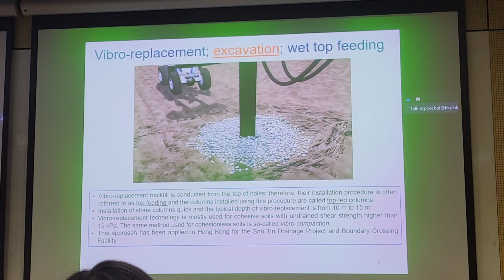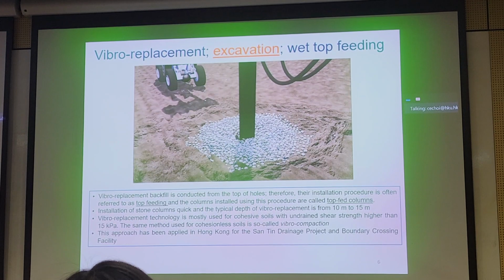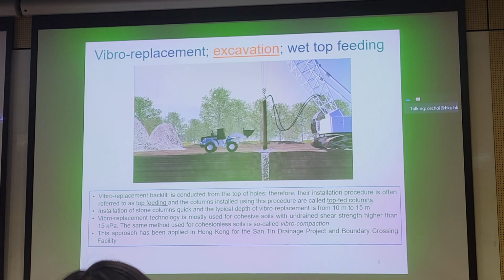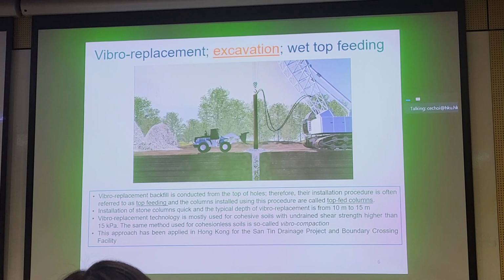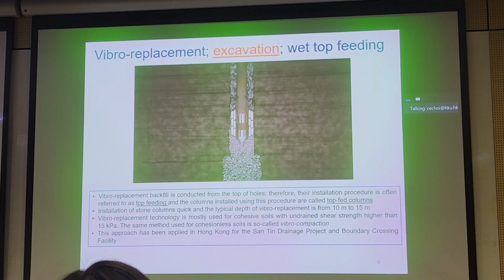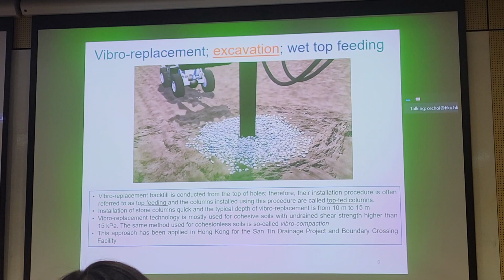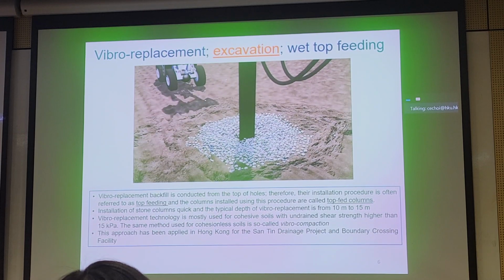We call this top feeding because you have a bobcat there, or a small excavator, essentially feeding gravel from the top, and it just falls down into the hole. This probe is being raised and dropped by a very large-scale crane, and as you vibrate, lift it up, and drop it back down, you break the contacts between the gravel, and the gravel can settle.